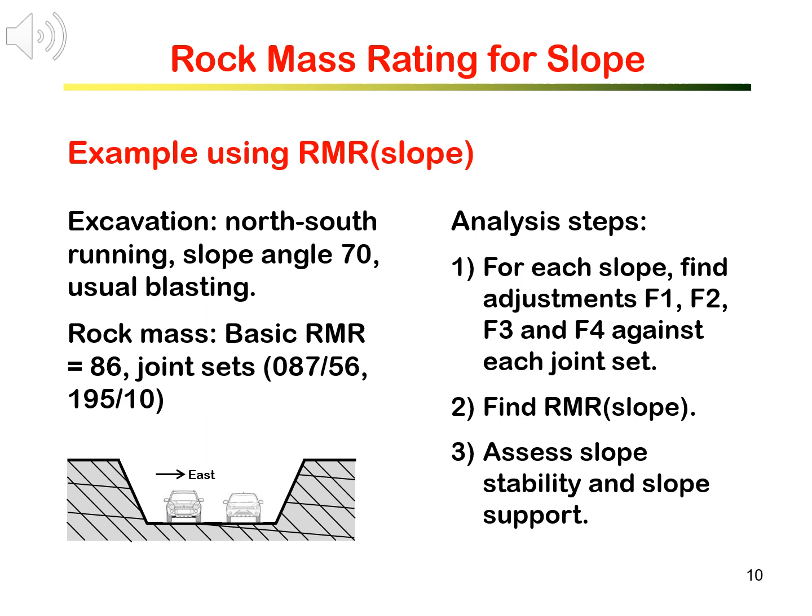I'm using an example here to reinforce the learning on using IMR slope. The problem is an old problem we saw at the beginning of this session. A north to south running road is to cut a rock hill. It will create two slopes. The left side slope is facing east, and the right side slope is facing west. The hill has the same rock mass, and the basic IMR of the rock mass at the site is 86.